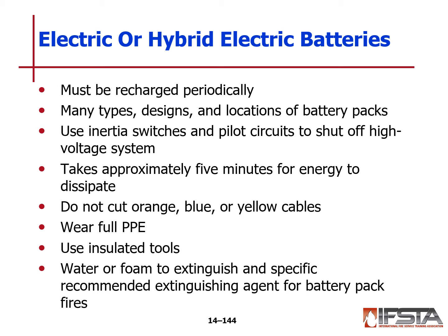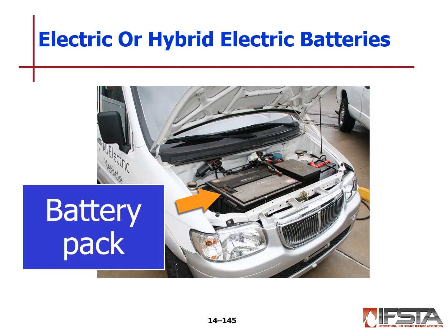Remember to not cut orange, blue, or yellow cables. They are high voltage cables, and cutting into them can be dangerous. Wear full PPE. Use insulated tools, any water or foam to extinguish, and specifically recommended extinguishing agents for battery pack type fires. Here's a battery pack that's located in the front. It's rather large. Though they're marked, you can see how well cased that is.